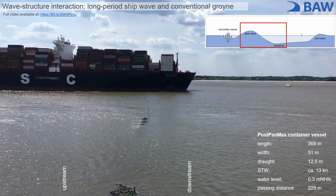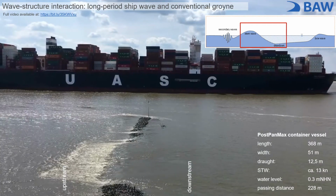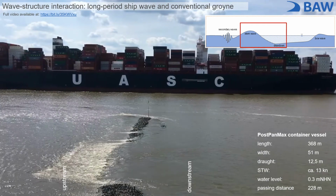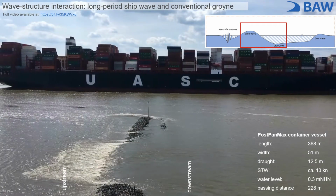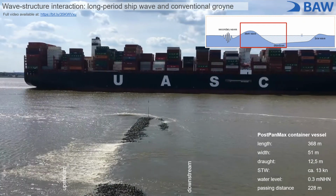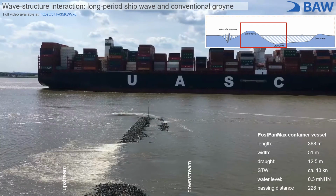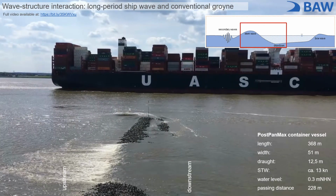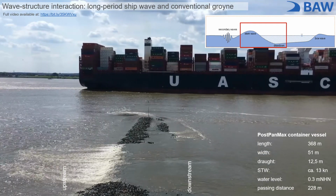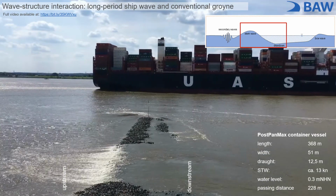As indicated by the red bounding box, our video starts in the drawdown phase and shows the arrival of the stern wave. The action of the drawdown is creating a water level gradient, causing overflow over the groyne and flow around the groyne head against the direction of travel. As we approach the maximum drawdown, we will begin to see a relatively rapid reversal of the water level gradient, as the drawdown, which is hydraulically bound to the ship, moves into the downstream groyne field.